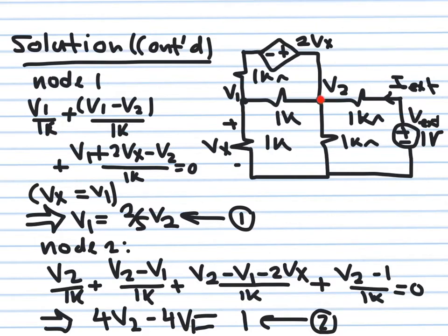We have how many currents flowing out from this node? 1, 2, 3, and 4. Someone may say, well, we have voltage sources, I may not be able to write the currents. No, you should be able to, because you have series resistances with these sources. These sources are benign sources. Every time you see a voltage source with a resistance in series, this means you can apply KCL without a problem. So this current flowing out here is V2 over 1K.